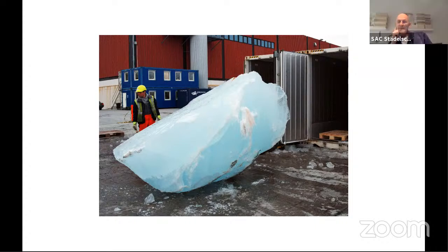Right. And in this case, your concrete, that slipped by me, I didn't get that. Your concrete is not reinforced, right? It is fiber reinforced. Okay, so you have small whiskers, glass fiber whiskers. Exactly. It can be not only glass fibers, it can also be stainless steel needles, which are often used, or carbon fiber. Or there are many alternatives, but in terms of labor, the fiber reinforcement, which you just apply in the batch, saves a lot of manual labor. In comparison to rebar, which needs to be laid out, especially in complex geometry, the rebar or regular cage reinforcement is just a great deal of labor.